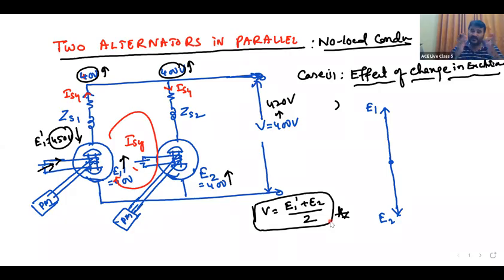Okay? Yes. There is a question. What is the question? You know, in a previous examination: two alternators, G1 and G2, are connected in parallel. If the excitation of G1 is increased, to maintain the same rated terminal voltage, the excitation of G2, the second machine, has to be decreased, increased, or no change, like that. What to do? The excitation of the second machine has to be reduced. It is an opposite action. When one increases, the other has to be decreased.